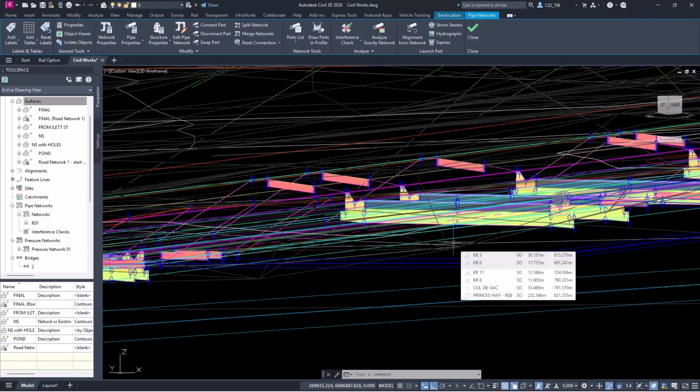That being said, though, if you're using Civil Site Design, you can generate those objects from your civil site models. So Civil Site Design has the ability to export the corridor out from your road model that you've set up, and your drainage networks that you may have set up in the pipes can actually be exported out as Civil 3D pipe objects. So you can get it in there. You just have to do it as that double step.